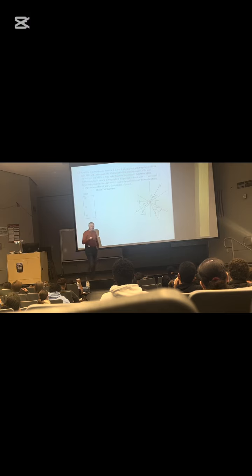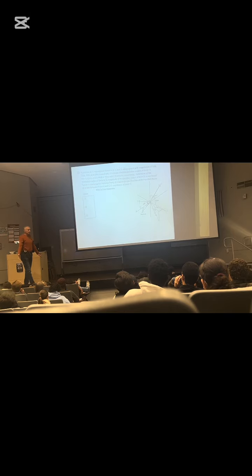Do you know how to find an angle between two vectors? Yeah. How? FD dotted with FC, divide by the magnitude of FD, the magnitude of FC, take the cosine inverse. That's just an application of the dot product we just discussed today. Notice it's on the test. It was on the old test. Yeah? You with me? Who's not with me?